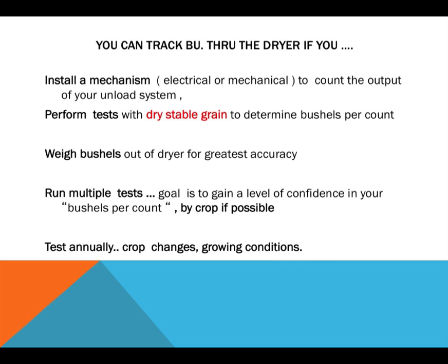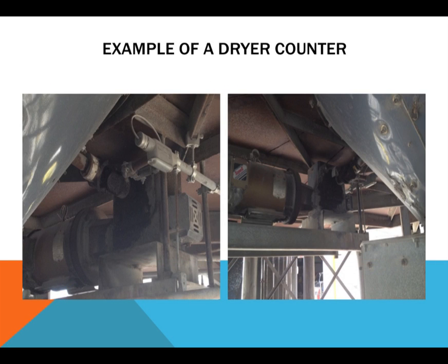Most of your net houses say you brought in 1,000 bushels of wet grain. It's really only 850, and you only put 850 in the book. And they don't ask you to track the shrink. I came from an organization that tracked every shrink: dryer shrink, aeration shrink, mechanical shrink, mixing shrink. How many more were there? And then it went on forever. But that's why it was important to go through this process.